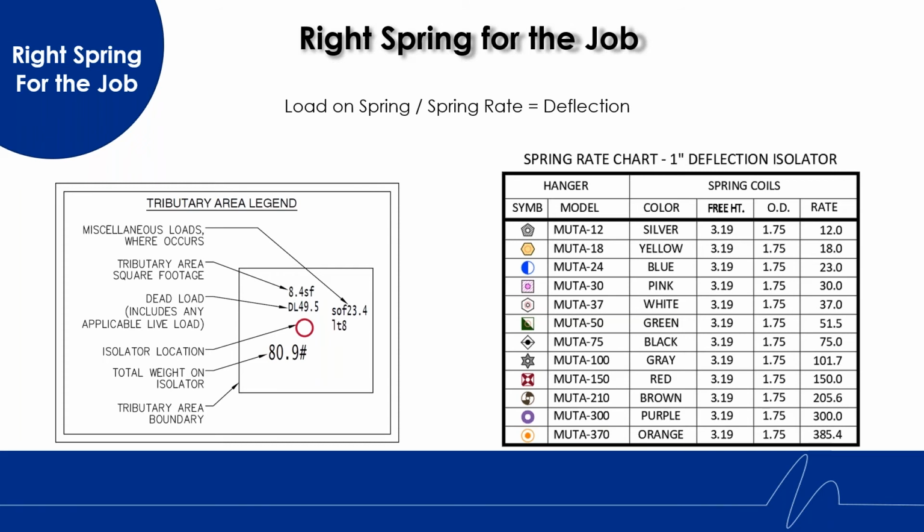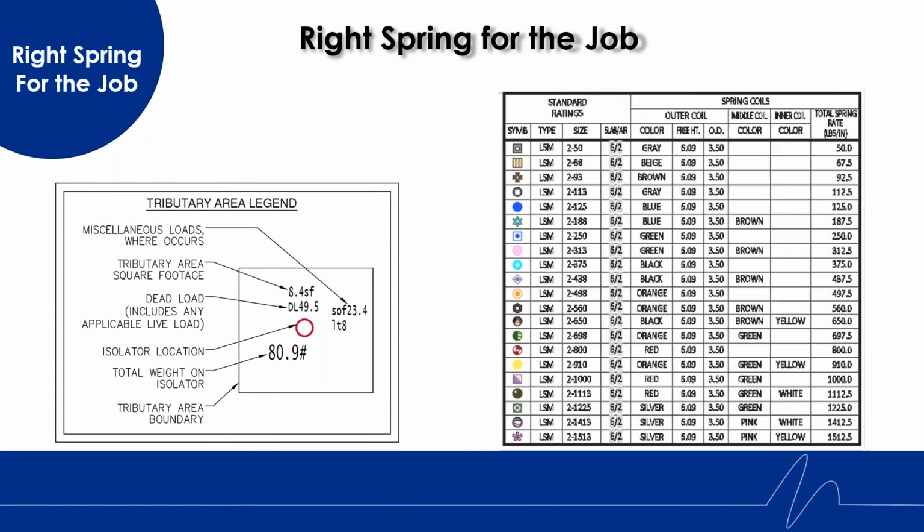It is important to note the spring deflection family that you are viewing and selecting. The chart being shown is for 1-inch deflection isolators. This chart represents a 2-inch deflection isolator family.